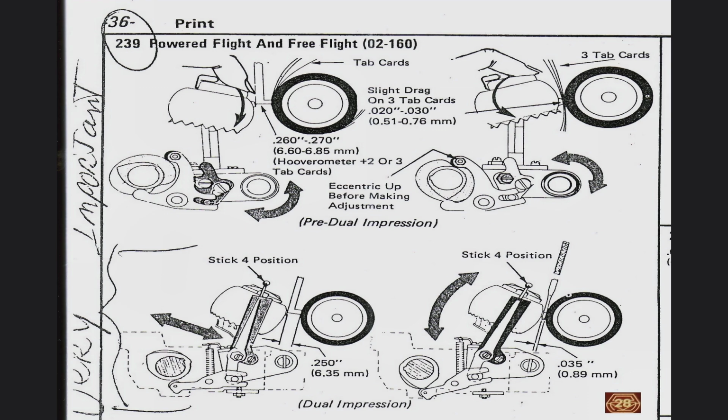While this is a lot of information for just one adjustment frame, you need not let it confuse you. The first adjustment is simply that of the rest position of the rocker, and the second adjustment determines the maximum active position of the rocker. For both, the platen, or the multiple copy control lever, must be in position A.